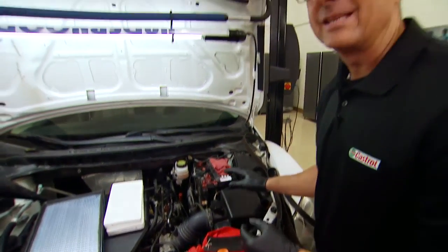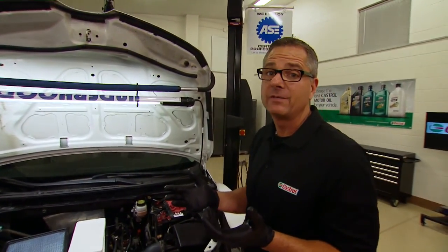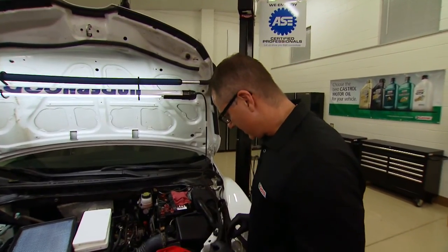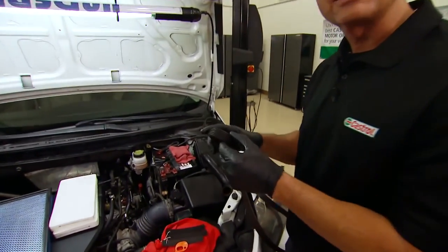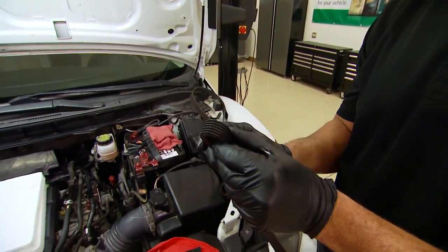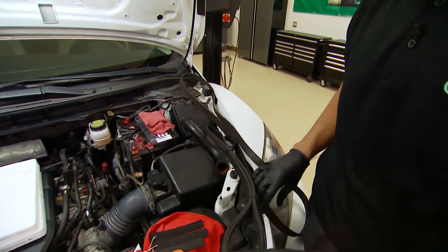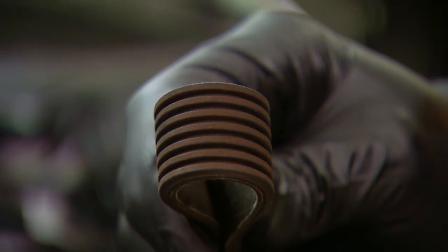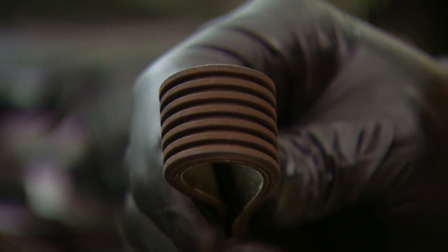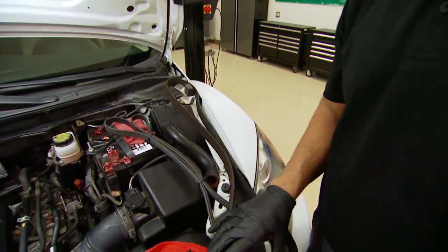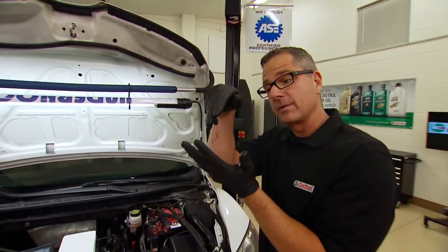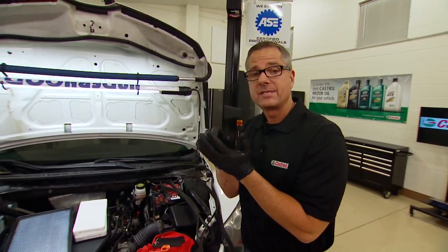And most importantly, the belts. Now the belts, there's been a lot of evolution in the belts. There used to be a neoprene belt, and the neoprene belt looks like this. And everybody remembers we would squeeze it and just look at all the cracks. Well, you can't do that anymore because the new belts are EPDM material. And EPDM material, think of an analogy of a tire. A tire wears out, the grooves start to go down and down and down. That's what happens to this belt here.